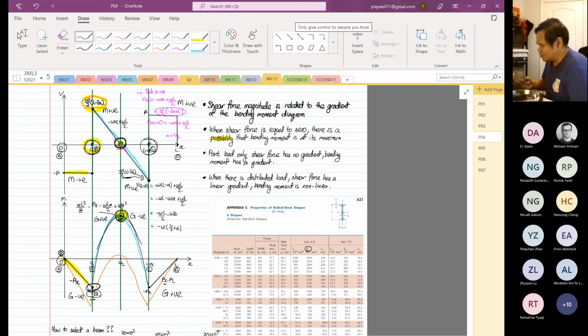Okay, so based on bending moment. This is just based on bending moment. Why just based on bending moment? Because the bending moment is at maximum, shear force is at 0. If you pick elsewhere, I'm not saying that you cannot pick elsewhere. You can pick elsewhere, but the result is you have to combine with Mohr's circle.